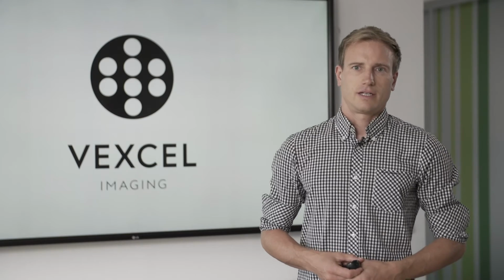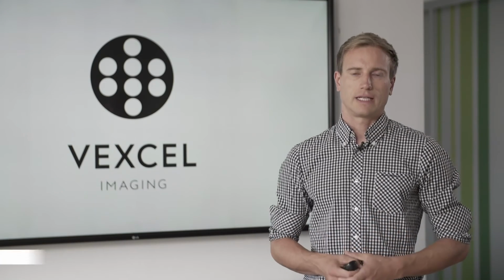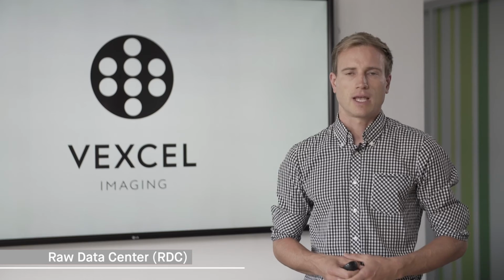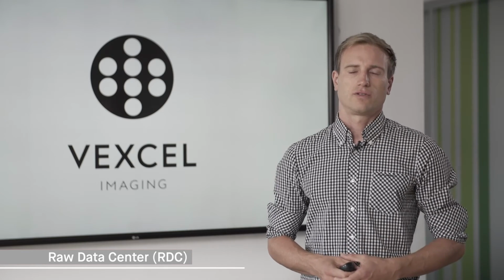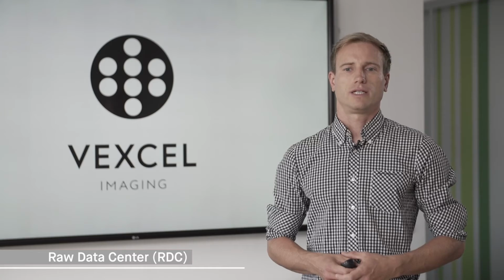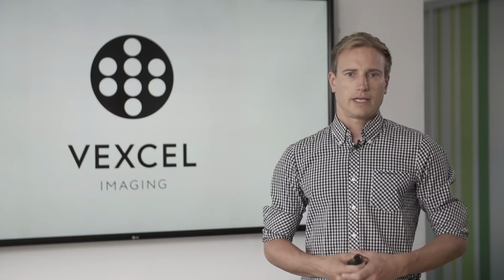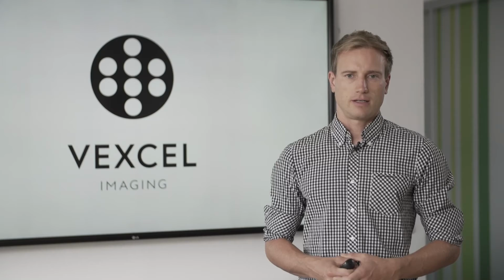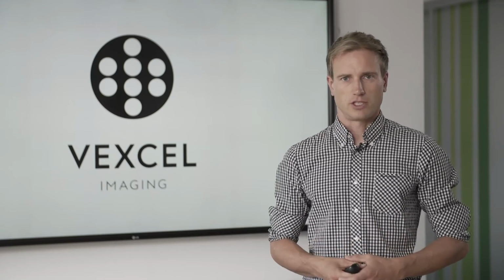Let's have a look at the UltraMap software modules in detail. The UltraMap workflow starts with the Raw Data Center, the RDC, and this tool allows a monitored and verified transfer of the raw data from the camera data unit to the file server. Once all the raw data is on the file server, then in the post-processing, the camera calibration is applied and the stitching of the images is done.